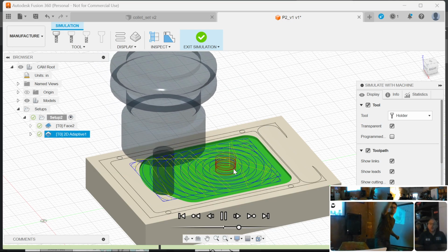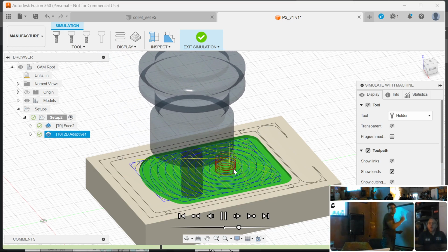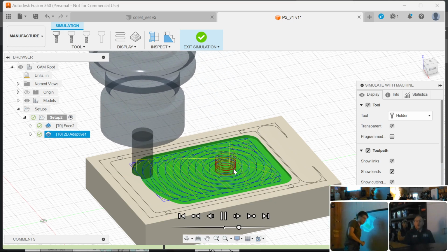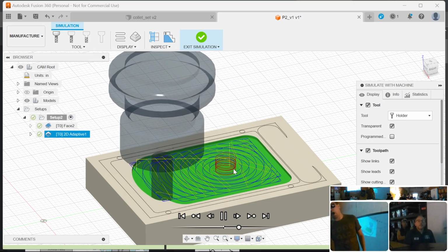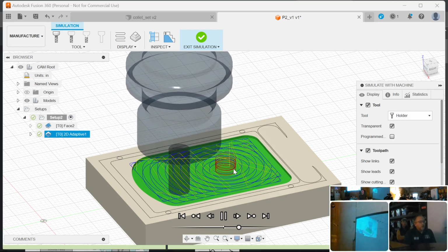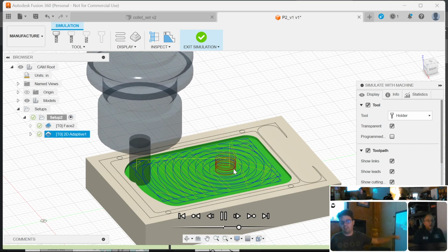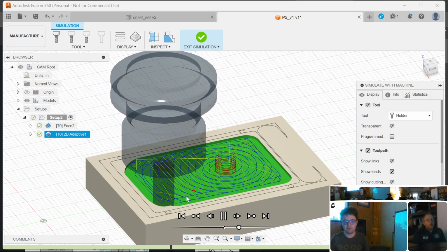And so it's moving on a 2-degree ramp, and that's enough to guarantee that this leading edge will have cleared before the center gets there. You can often use like 10-degree ramp angles for most bits and be completely fine. 2 degrees will work for anything out there and is a very safe way of doing it.